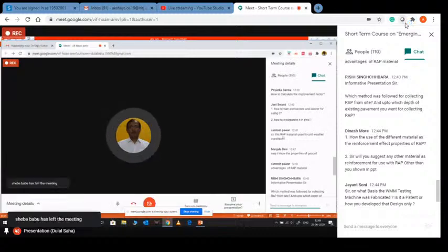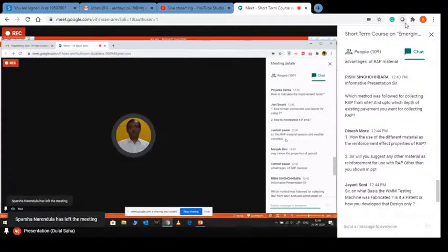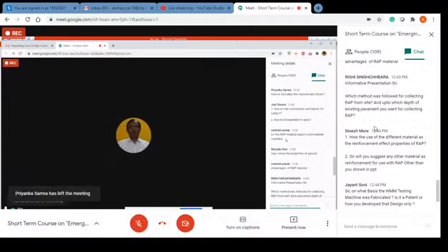The next question is from Mr. Santosh Pawar. Is RAP material used in cold weather condition? Sir, I could not understand your question probably, but let me assume something and then reply. As I said, RAP is such a material that it can be utilized in each and every layer of bituminous material. It can be utilized in bituminous mix, hot mix we call it. It can be utilized in base, it can be utilized in sub-base, and in many places it is utilized in subgrade also. In one of the World Bank projects in Gujarat, GSSP2, Gujarat State Highway Development Project, where I was a part of the mission also, they have used it in subgrade also.